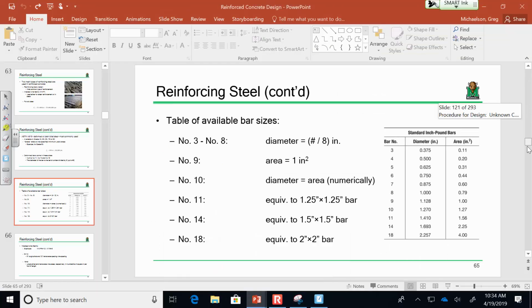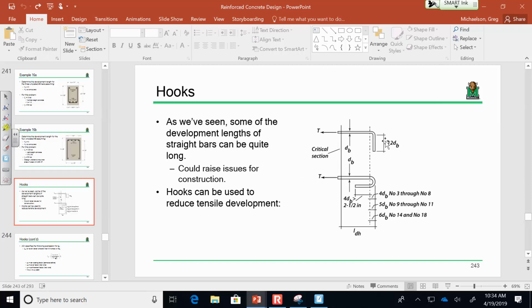Well, first off, I have a couple answers that would completely define the geometry, and we'll see if that answers it. So, when I say the developed length of a hook, I'm starting from the point where it embeds to the outermost dimension. So that's the development length. From here to here, or here to here. So we're talking about, if I can put it on the screen, from that edge to that edge, like inside of the red to inside of the red.